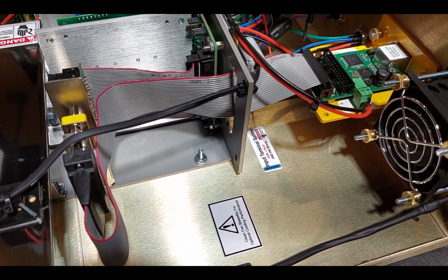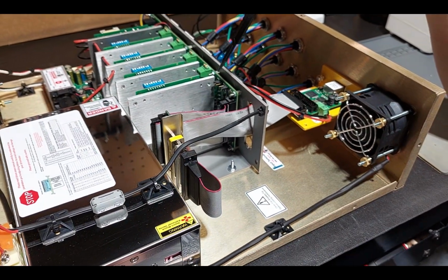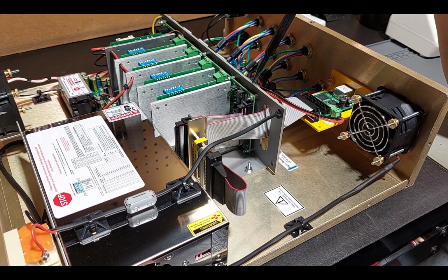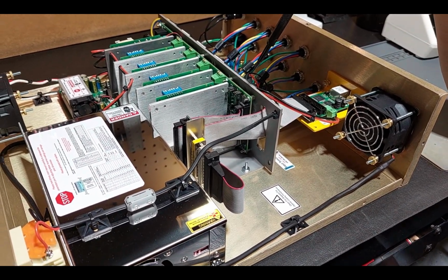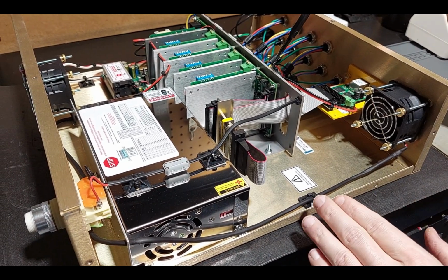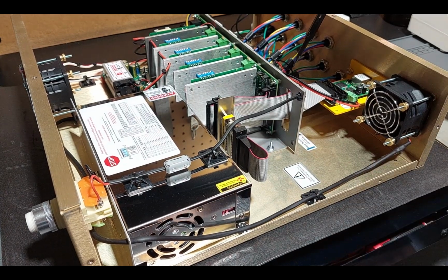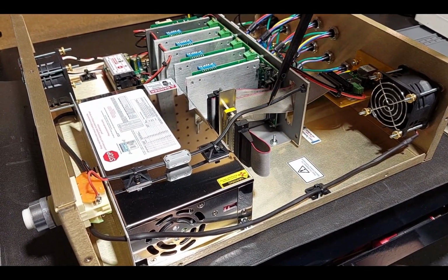And just so all of you know, your best friend when it comes to cables in general is heat. Applying heat, and when I say heat, reasonable heat, let me be explicit, no more than probably 150 to 200 degrees just to warm them, and it allows you to mold the cables. And it's the same principle I did here with the heat shrink.